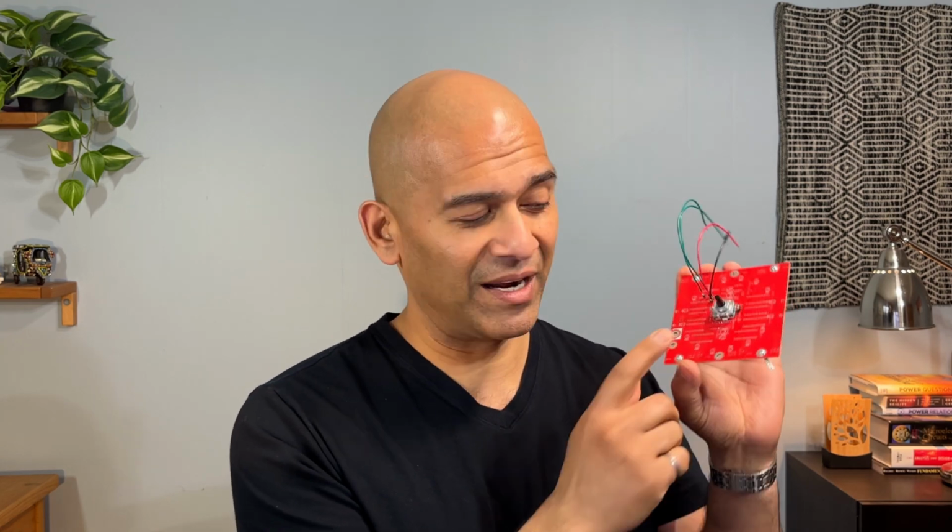Now, the other thing to consider is the specific rotary encoder that we're using here has these real chonky pins, which don't fit very well into the breadboard. So your rotary encoder may have some smaller pins, which would fit just fine. So you can use that. But for this, I actually had to solder it to a separate board. Now the board that we're using here is just a leftover board that I had from a previous design, which had space for that rotary encoder. And in the back of the board, you'll see that I put in the 4 resistors and the 2 capacitors right onto the board, so we don't actually have to put them onto the breadboard.